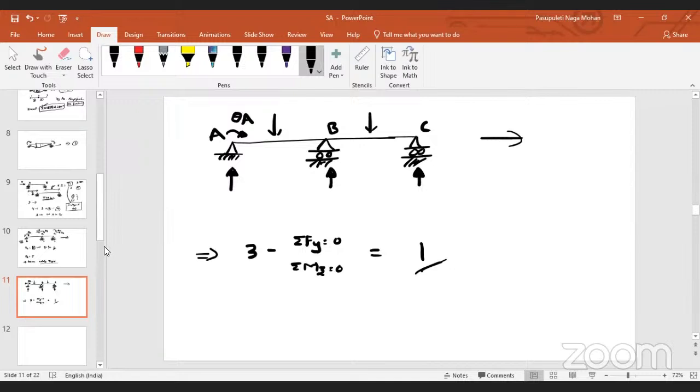How many unknown displacements are possible? One or two? One, sir. Why? Because, as horizontal loads are not applied, as horizontal forces are not there, there is no point of horizontal displacement. Moment only, sir. So only rotations are possible. Rotations are different, movements are different.